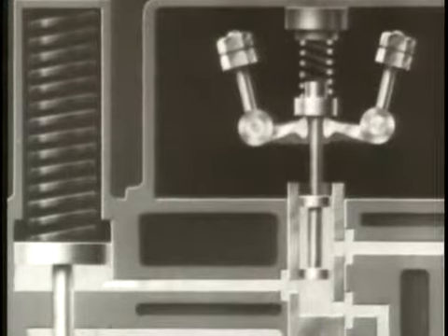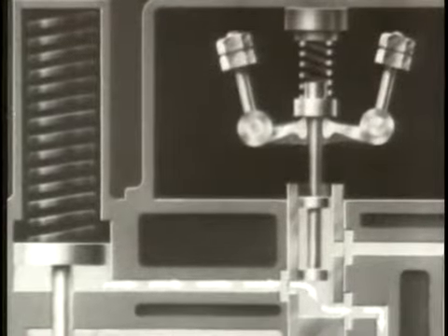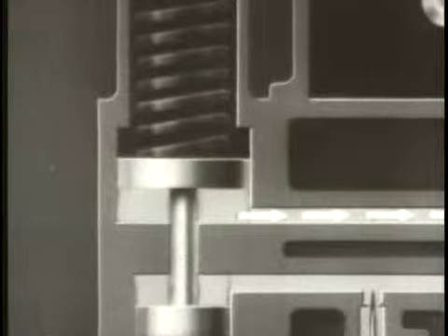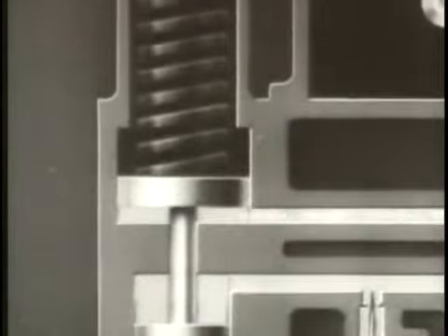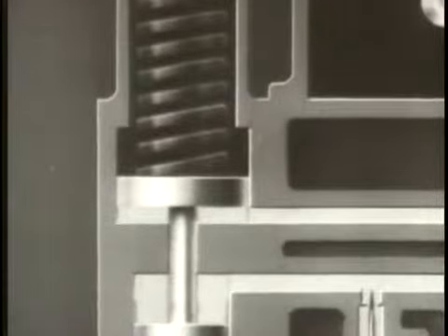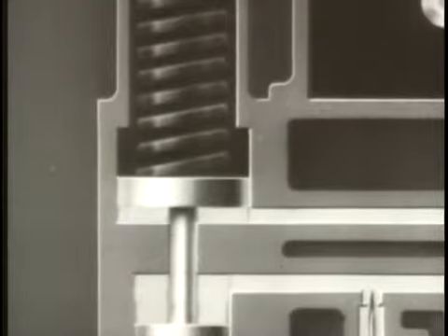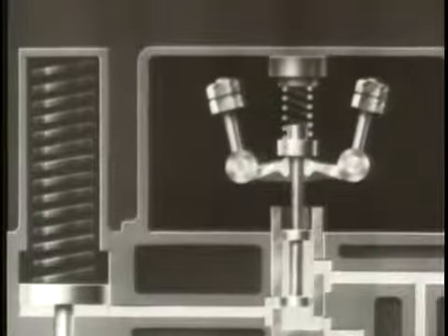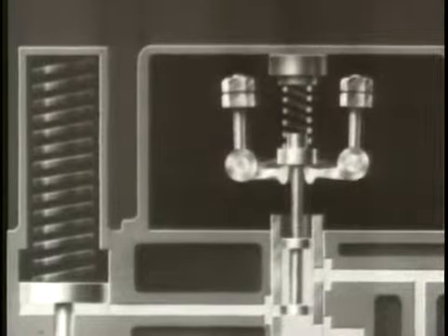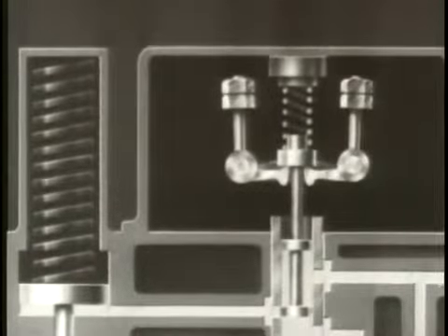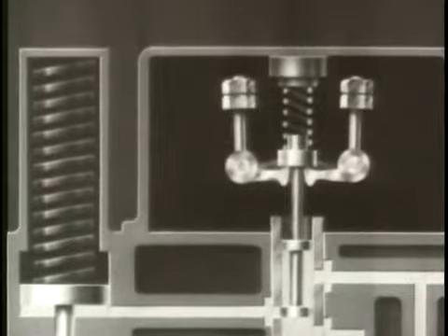and oil from the power cylinder is now allowed to flow through the pilot valve cylinder into a drainage passage to the oil sump. The power spring forces the piston down, actuating the linkage to the fuel system controls, and the supply of fuel to the engine cylinders is diminished. As the engine speed returns to the set rate, the flyweights resume their original position, and the pilot valve plunger again covers the port.